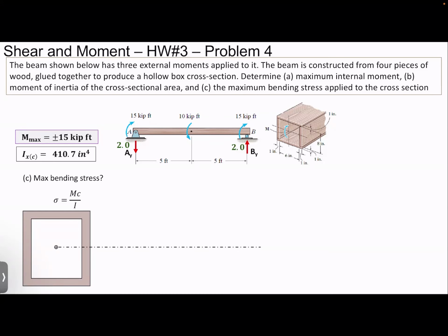Like, imagine this is the place here. This axis is coming out of the centroid and the stress is applying normal to this force. So this is called our neutral axis. This is out of the cross section at the centroid. The moment is being applied across that axis, and it produces an axial stress, or a stress that is normal or perpendicular to that cross section.